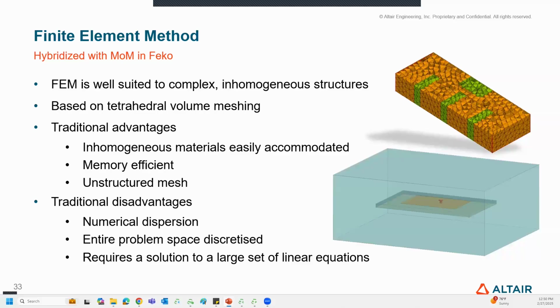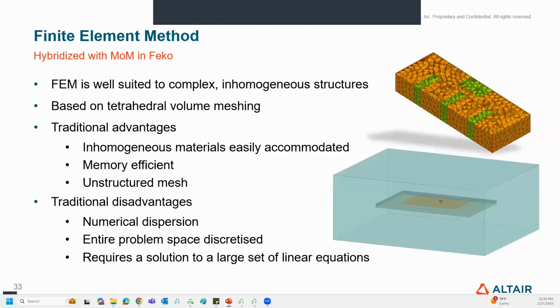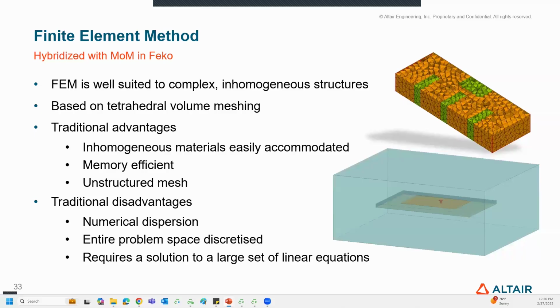But let's say you have an extremely complex antenna design with many different dielectrics, then method of moments will start taking more computational resources, because when multiple dielectrics are involved, the number of unknowns is automatically doubled for method of moments. So for that case, when you're dealing with complex geometries including dielectrics, I would recommend using the finite element method. And it's easy to switch between different methods in FEKO. They're all available within the same software suite.